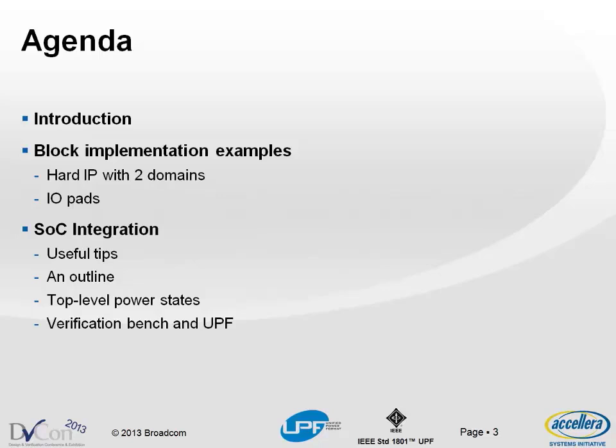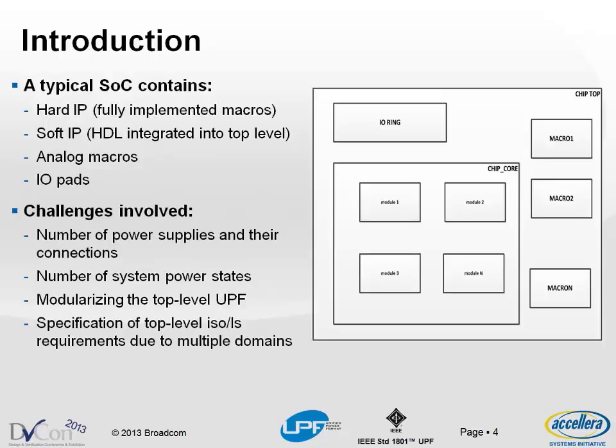So a typical SoC consists of hard IPs, and John just mentioned how we could build a hard IP with an ARM core. It also has a lot of soft IPs, and soft IPs are typically HDL, which we directly integrate at the top level. In addition, you could have plenty of analog or mixed signal macros, which you get as simulation models. And then, of course, you have all these I/O pads because you have to interact outside the chip. And I/O pads are interesting because they typically have multiple power pins. So we now get to see the whole gamut of all different types of implementations at the top level.